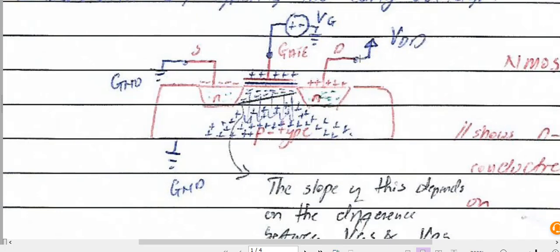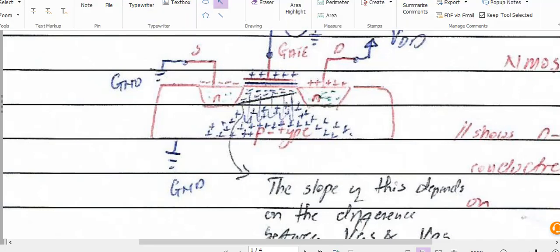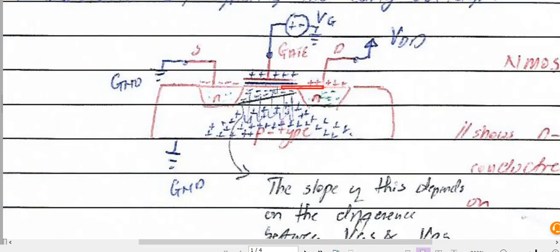Now, as you can see, in this model there are no resistors whatsoever. It's just a voltage source in a MOSFET device. Assuming that Vg is constant still, if we did not plug in any resistor at any point in here, we are going to have VDD being equal to VDS. Now let's define a new voltage. VDS is the voltage between the drain and the source. This voltage is the voltage dissipated in the transistor. So VDD is the voltage that you're supplying, and VDS is the voltage that is dissipated in the transistor.